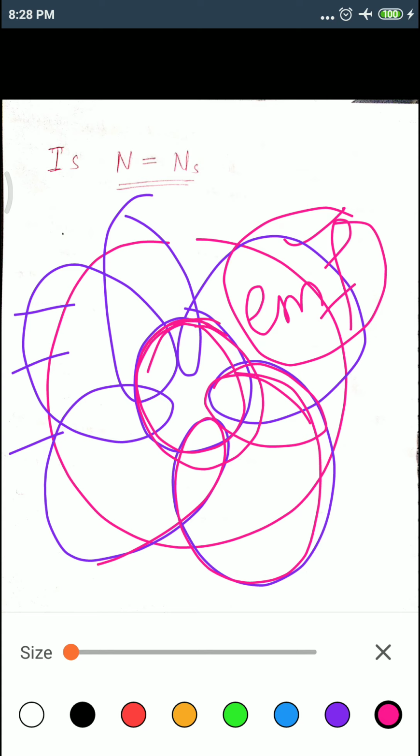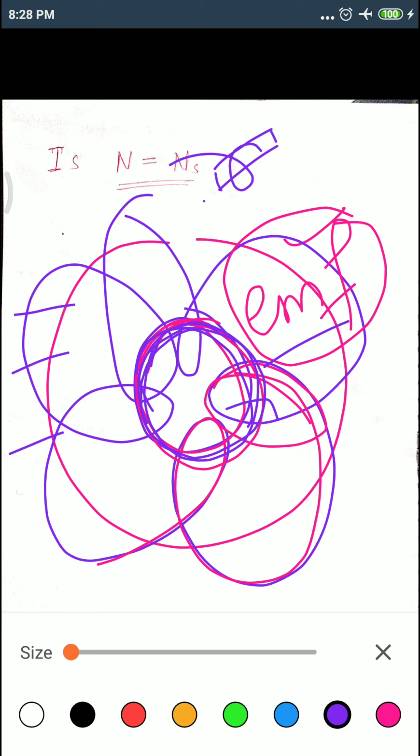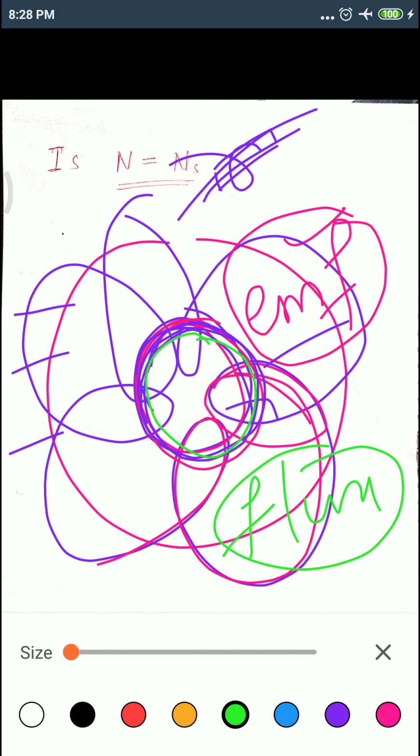Once the rotor gets EMF, what happens? The rotor EMF allows current to flow through it, which is called the rotor current. Once the rotor current starts flowing in the rotor, as we have seen, any conductor carrying a current produces a flux. So the rotor starts producing its own flux, called the rotor flux. Now this rotor flux and the RMF interact.